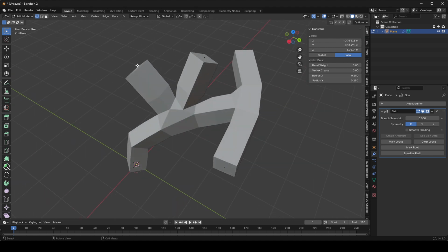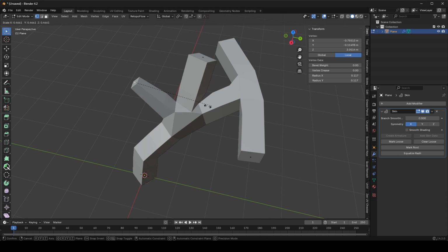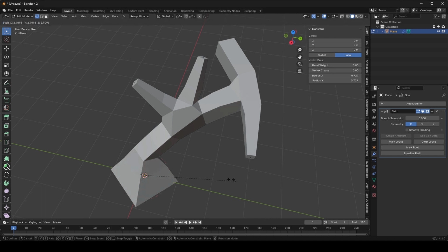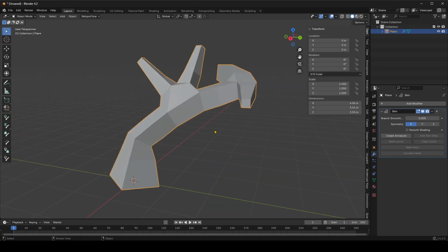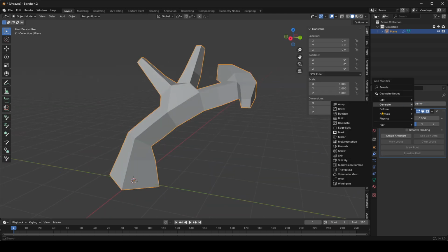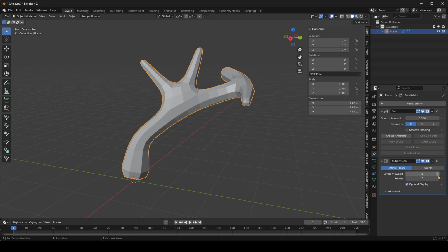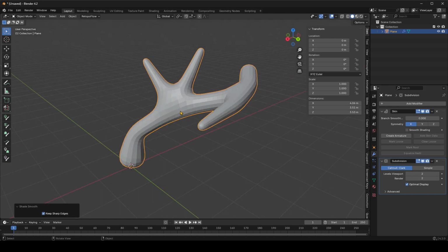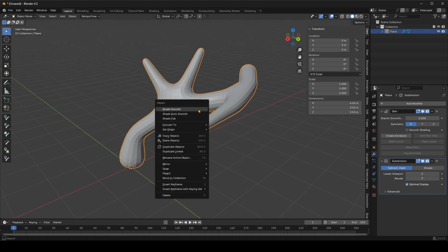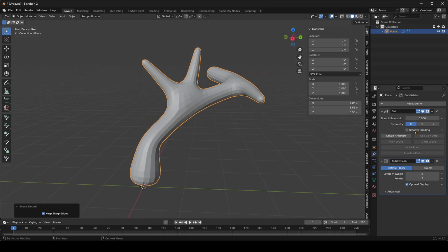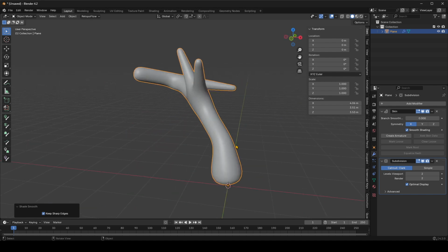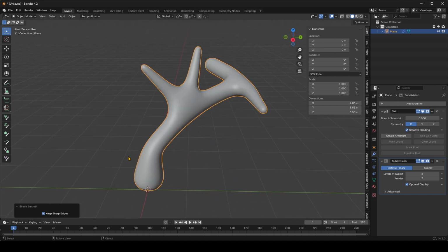And then if we want to adjust the thickness of this, it's Control A. So it's different than the curve. Control A will adjust the thickness. And if we wanted to make this more round, we could just add a subdivision surface modifier. Right, and that's those tools. So you just have to show me that you understand how to use them, and that's it.